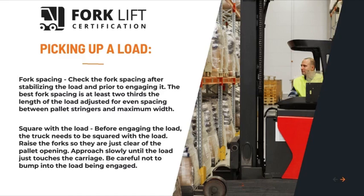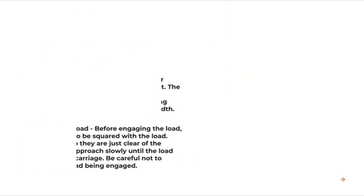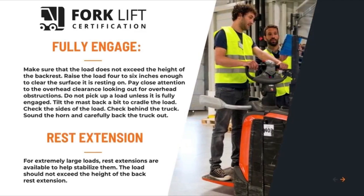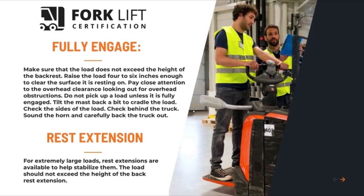Raise the forks so they are just clear of the pallet opening. Approach slowly until the load just touches the carriage. Be careful not to bump into the load being engaged. Fully engage. Make sure that the load does not exceed the height of the backrest. Raise the load 4 to 6 inches, enough to clear the surface it is resting on. Pay close attention to the overhead clearance, looking out for overhead obstructions. Do not pick up a load unless it is fully engaged.